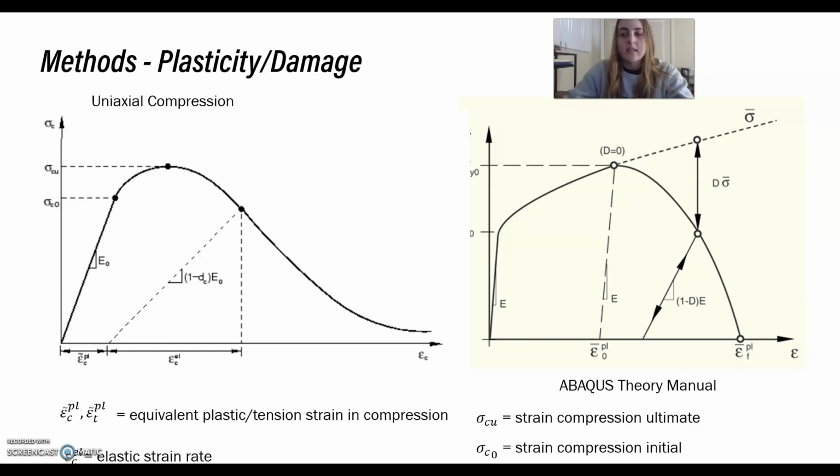This is the elastic modulus that you can see whenever there is accumulating plastic deformation. When damage begins to occur, the stiffness matrix alters and decreases. Ultimately the modulus, this slope, decreases, and overall we can see the trend changing from each point on this curve. That's really important when we look at the stress versus strain in our Abaqus model and in the implemented solver.